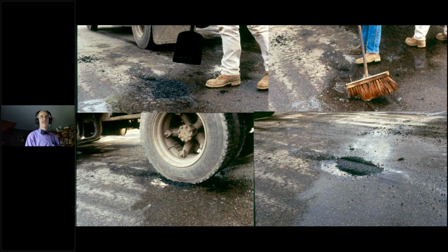And it can work even on a gravel road. I've actually used these polymer patches on gravel roads, and it actually works. But the key is get that truck, roll over it, and your truck tires actually help activate the polymer. So pick a good technique and do it well. Okay.